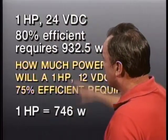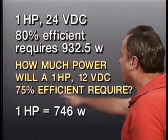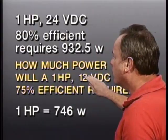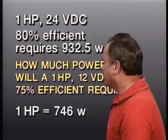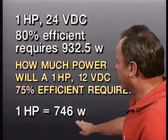They give you that information, then they ask you this question. They're going to ask you, how much power will a 1 horsepower, 12 volt DC electric motor require if it's 75% efficient? How much horsepower or watts will be required to produce that 1 horsepower? And they also tell you that 1 horsepower equals 746 watts.